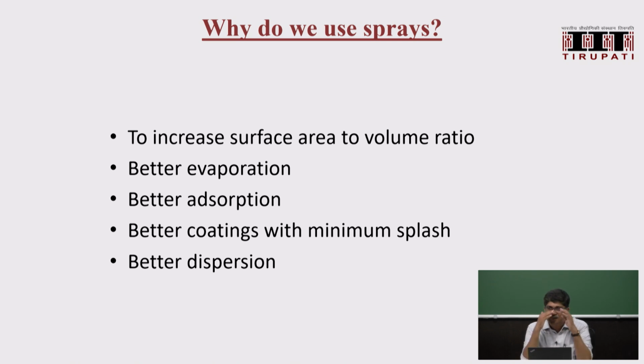Again, in combustion, if you take a cylinder or a gas turbine, usually the injectors are at the surface or at the center, one point, or at most a ring, and then the spray has to spread across the chamber. So the drops need some momentum to penetrate. If you make too fine drops, they will not have momentum.